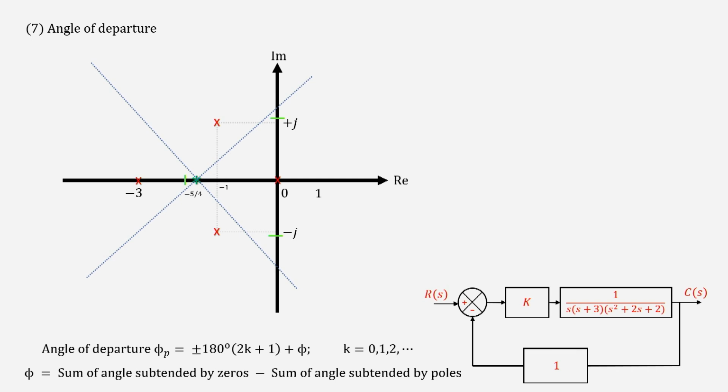So, in this example it will cut the imaginary axis, so I am giving you the rule. In general, when you do not know whether it will cut or not, you have to apply all the rules, go with each and every rule and find out the values. If it would not have cut, you would not have got a value of k. In this case it cuts, that is why you got a value of k for which the root locus cuts the imaginary axis.